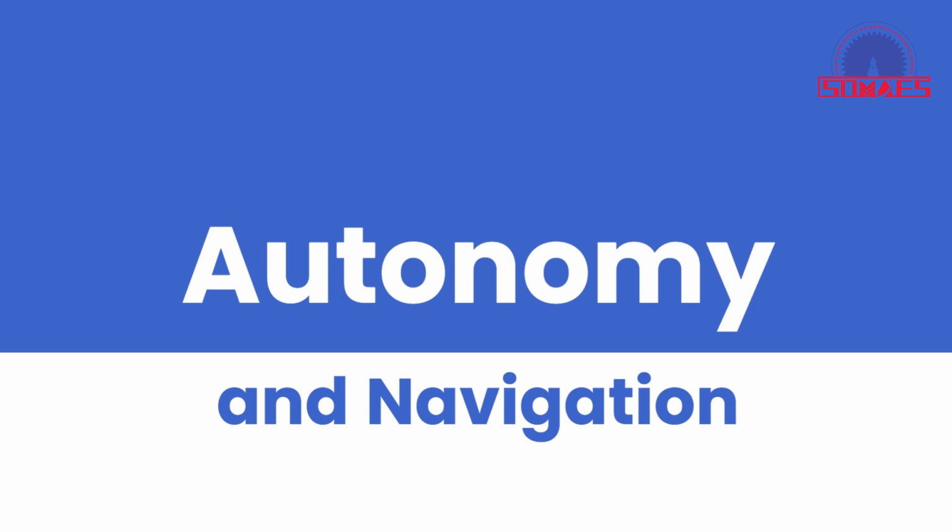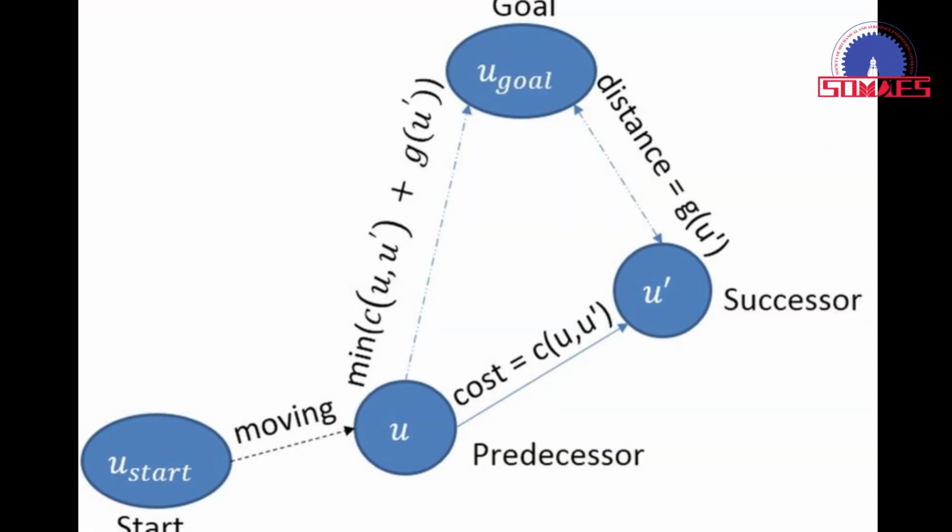For these kinds of situations, D* Lite, a smart pathfinding algorithm for robots in changing environments like disaster zones, is used. D* Lite is an algorithm which tries to find the shortest path from one point to another. Let's take a simple example where a surveillance drone finds out a person is trapped inside a house or a certain node in a given graph, and the robot should reach this place as soon as possible. At first, the algorithm draws an initial path. It first finds the shortest path from the goal to the start, so the robot always knows where it needs to go.